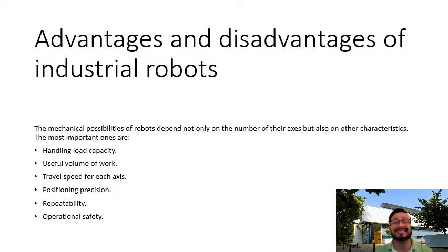Although the robot is itself a flexible element, it is also necessary for its gripper hand to be efficient and flexible to grasp all the parts to be machined in the cell. Sometimes it is necessary to change the gripper to adapt it to very different parts. In this case, it will be necessary to have an automatic gripper system for the robot.